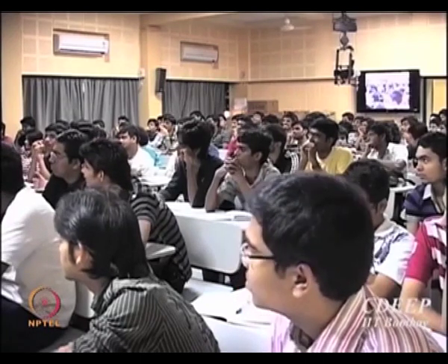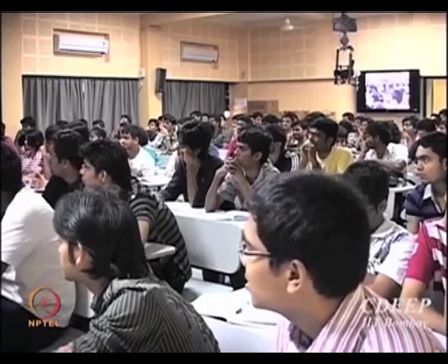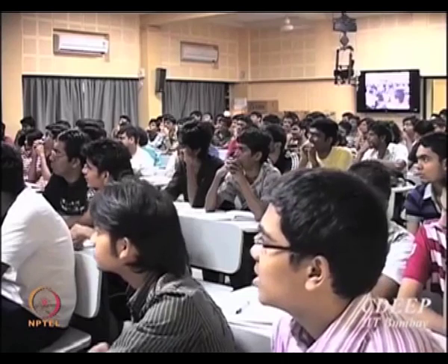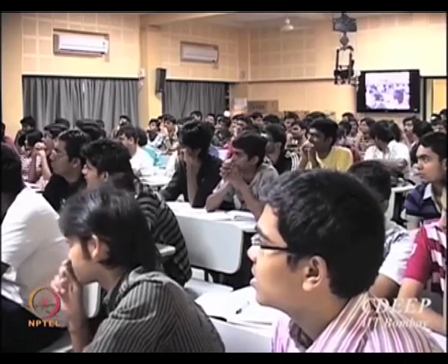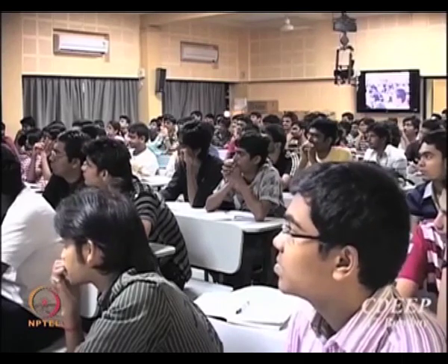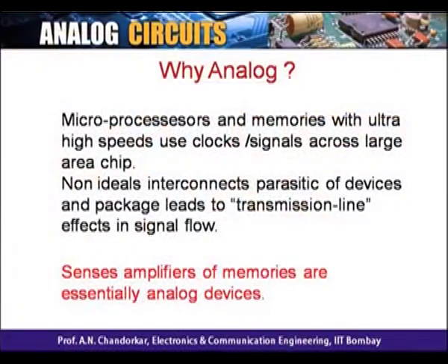That's something you must understand. We always think of wire as big wire, but here on the chip itself I have 1 kilometer. If that is so, the signal will not have integrity going from one point to the other. It's a lossy line. So the clock which is running from one end to the other actually drifts away.